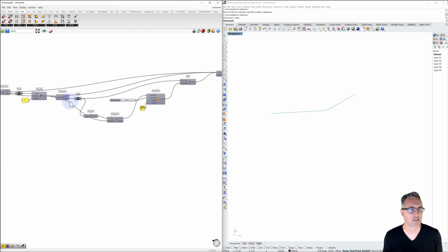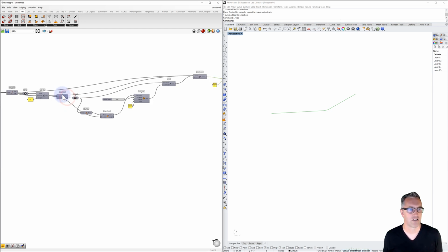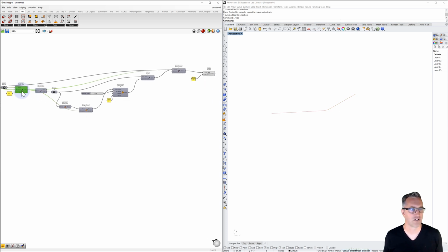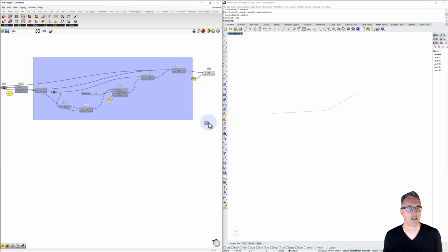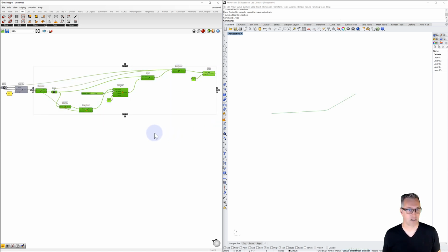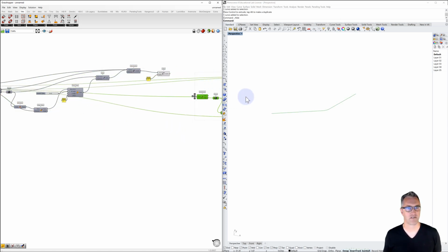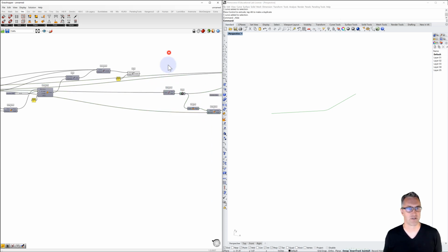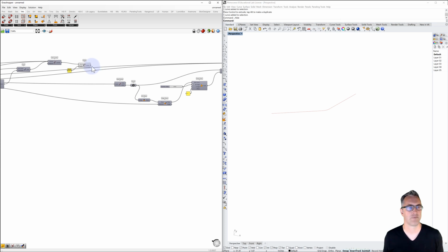But let's now start with, I think we can take everything after our first line. Copy it. We'll copy it to the right. I'll have to sort out some of these elements that are being dragged over. But we'll take our curve, and now we want to get the end point of our curve. We want to have an origin there, and the direction, and here we can see the importance of this plane. We want this plane aligned with this line.